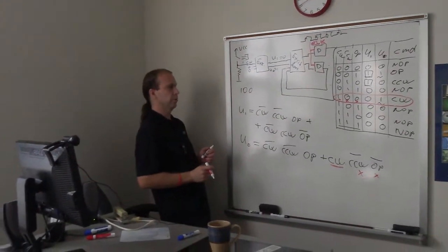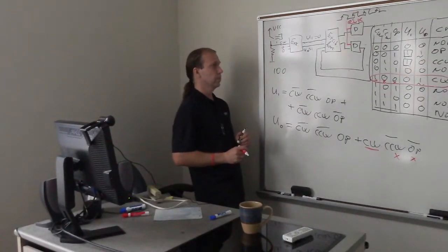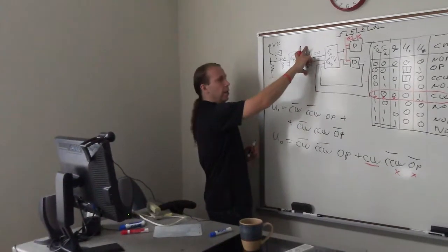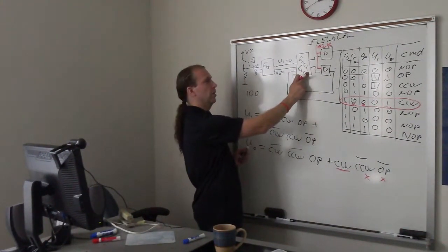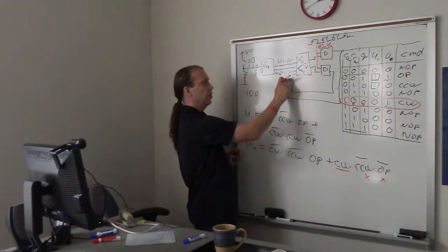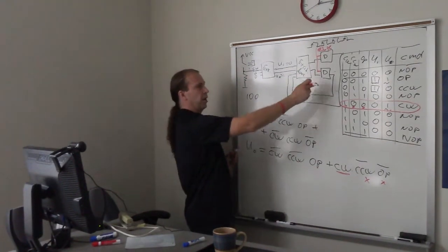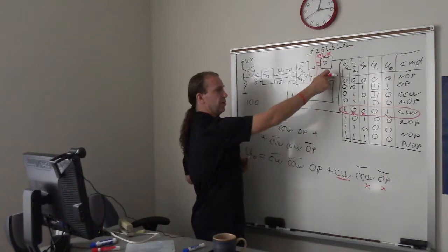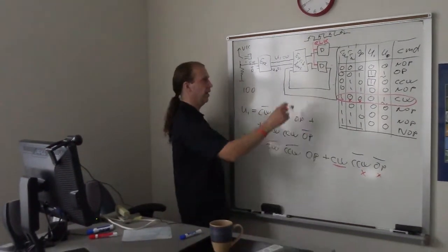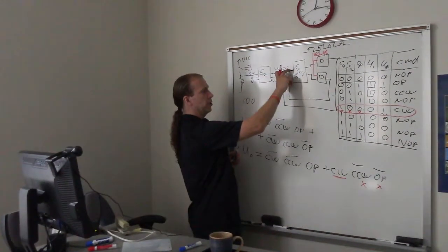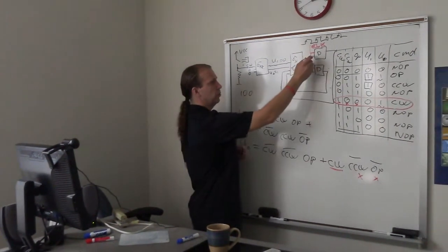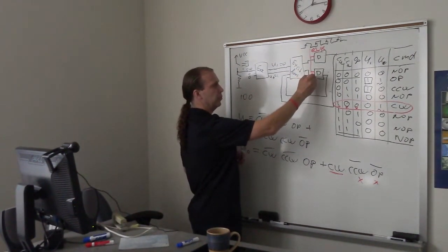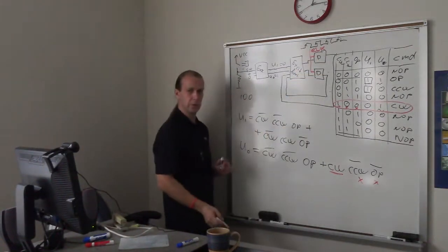That's the real circuit. Whatever inputs we generate are going to be fed into the excitation function logic, which has two more inputs, which are actually outputs of the triggers. And then the 4-input circuit will generate two outputs to drive the input signals of those two triggers.